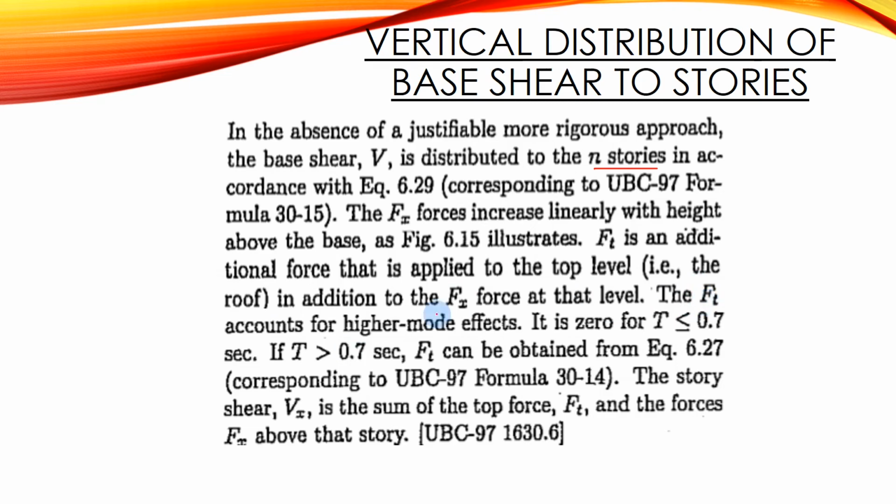Now the Ft accounts for higher mode effects. So it is 0 for time or period which is less than or equal to 0.7. Okay, so mao na siya 0 guys pag less than 0.7 second, less than or equal. Okay, pero pag mag-greater than siya og 0.7 ang period, then Ft can be obtained from equation 6.27. Okay, so the story shear Vx is the sum of the top force Ft and the forces Fx above that story.